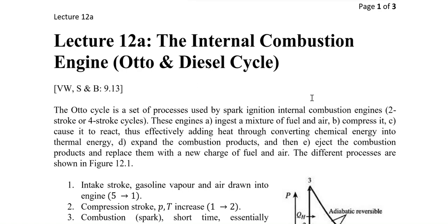But in a Carnot cycle, we also discussed that the engine based on the Carnot cycle would be impossible, and that impossibility is due to the heat addition and heat rejection, which is isothermal. So it is very difficult to have heat transfer to the system keeping the temperature constant, or heat actually rejecting from the system keeping the temperature constant. So in a real internal combustion engine or a real heat engine, these processes, the heat addition and heat rejection, are replaced from the isothermal to other processes.